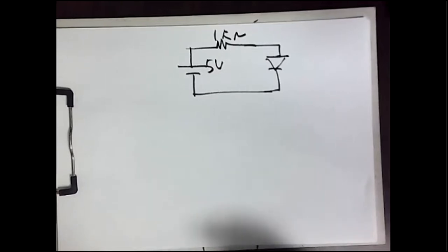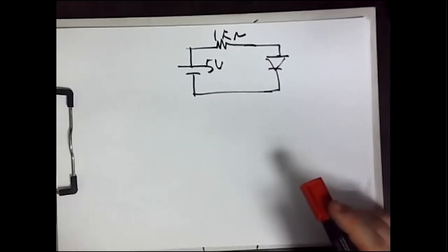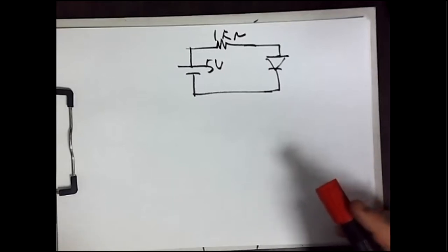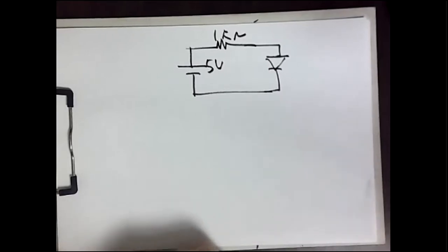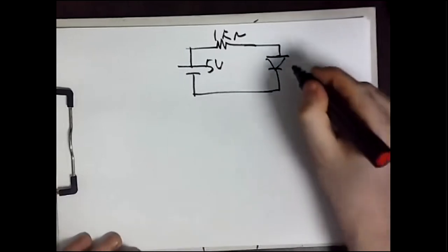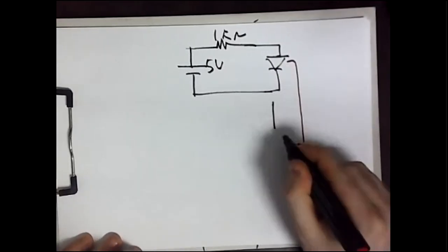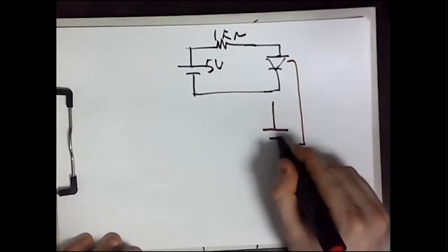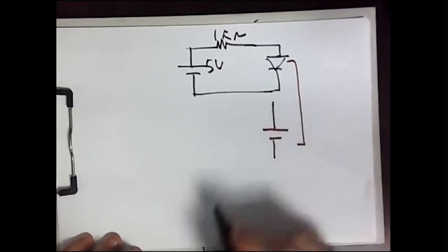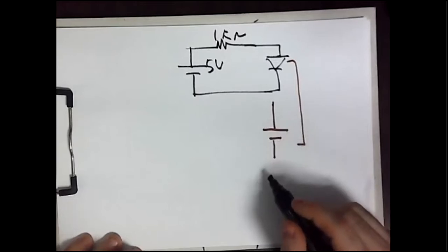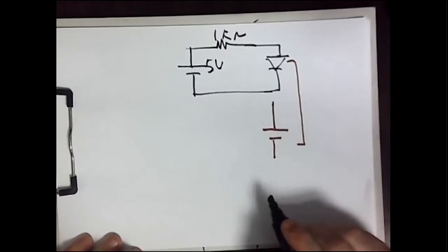Okay, that's perfect. Then it's now a constant voltage model. In the constant voltage model, my dear student, what you are going to do is replace this diode by a built-in potential battery in the reverse direction and a short circuit. That's all.